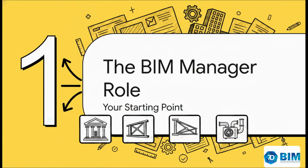Starting with Section 1, the BIM Manager role and choosing your starting point. Look, as the new leader of your firm's digital environment, you really can't just start from a completely blank slate. Your absolute first task is to pick a base template that makes sense for your specific discipline. So if you're in architecture, you start with the architectural template. If you're an engineer, you're going to grab the structural or mechanical template. You always want to build out from what you know best.